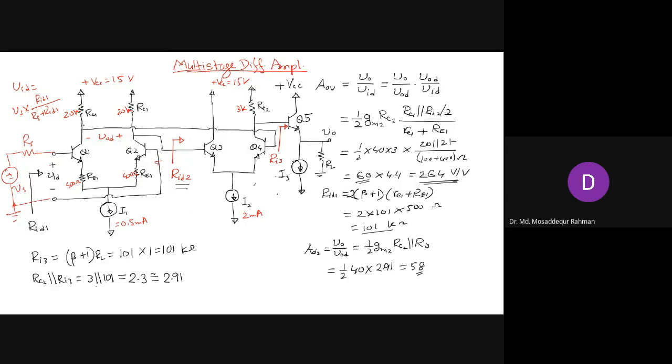So that's the purpose of the input stage. And then when you increase the input resistance, gain goes down. So we add this intermediate stage to increase the gain. And at the output stage, connecting the load affects the overall gain and reduces it. So we introduce the voltage buffer to minimize the loss at the output side.